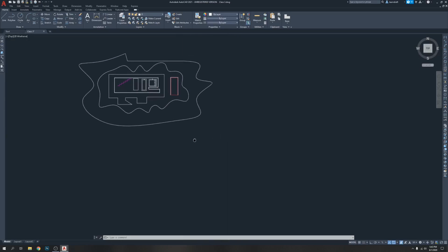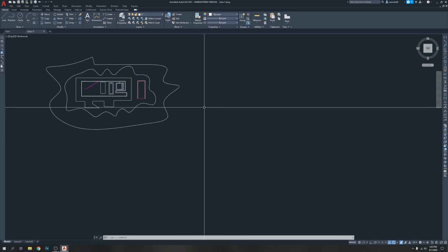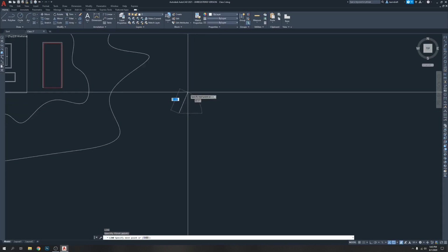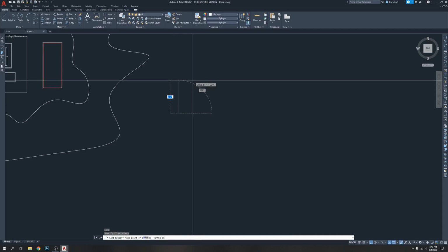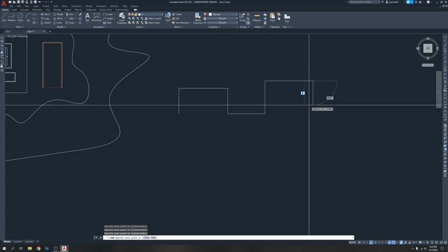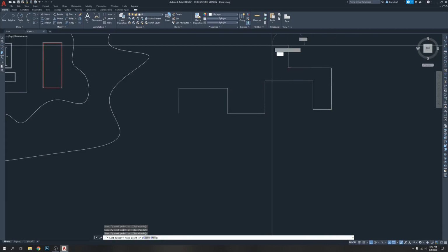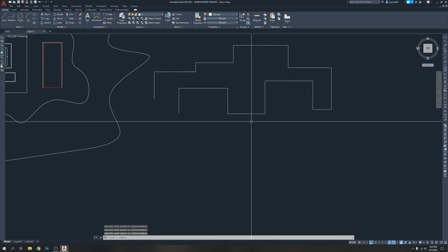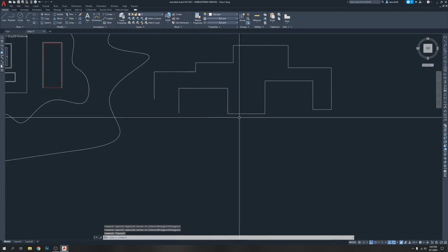Now PolyEdit, we're gonna try to draw some lines, and then we're gonna make it PolyEdit. So this is L, enter, click, press F8, go like, no dimension necessary, click, and press enter. So all are lines, they're individual lines.